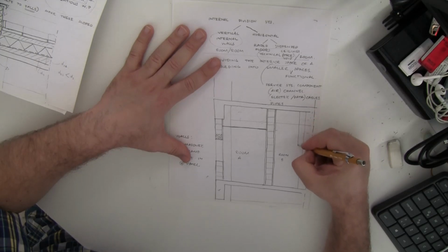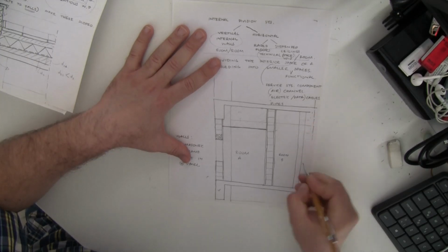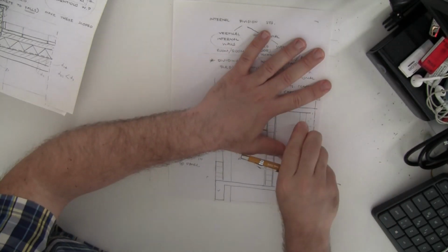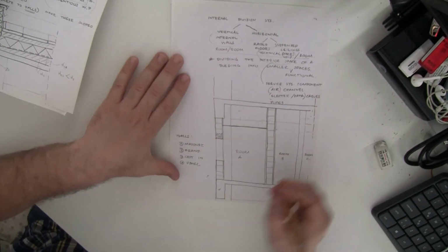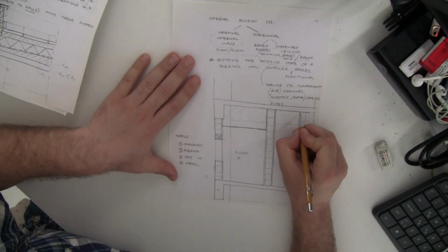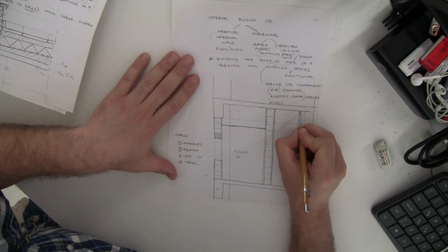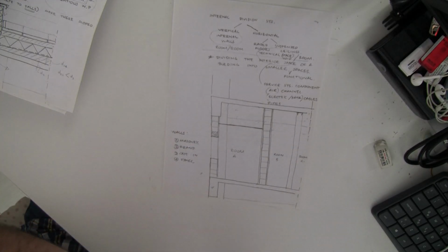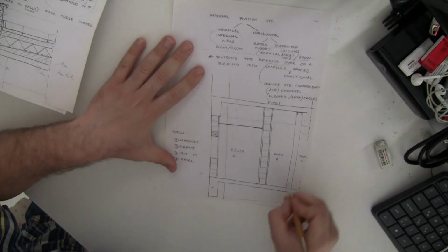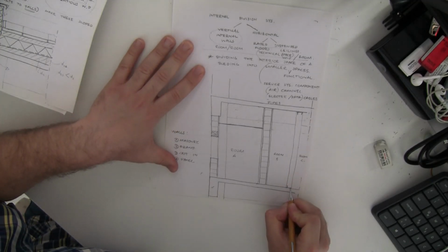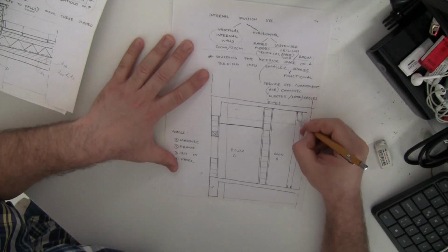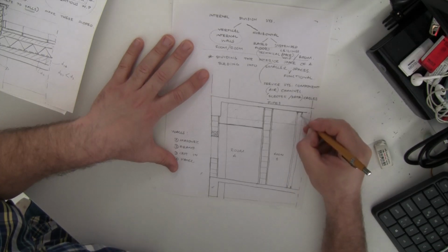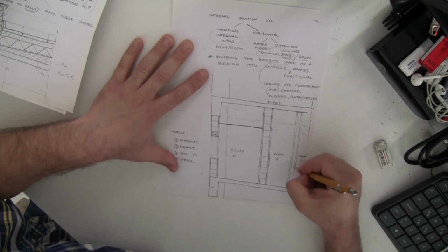Let's draw it here. And let's say that room C is a frame structured, lightweight steel frame structured wall. We are going to have a U profile there, and we are going to have a U profile here, and we are going to have our lightweight steel C profiles there.